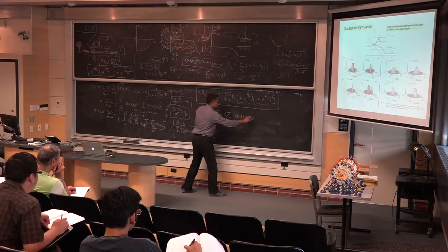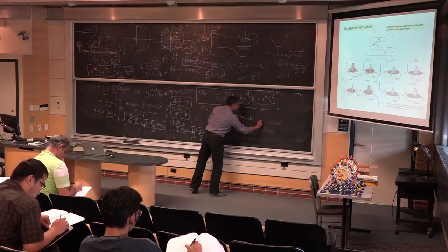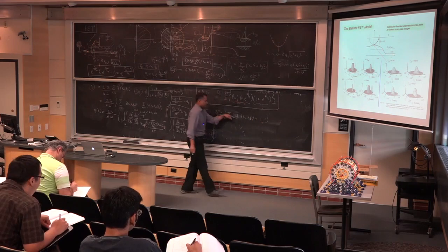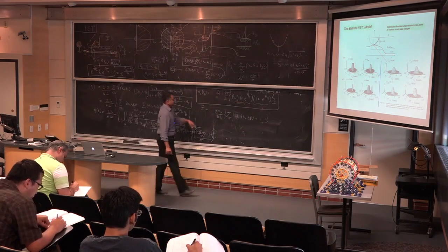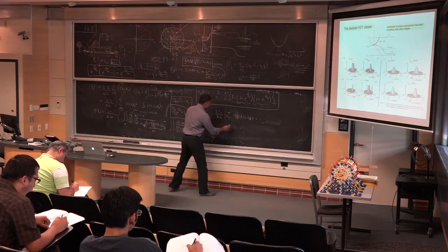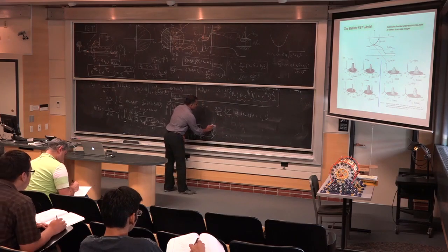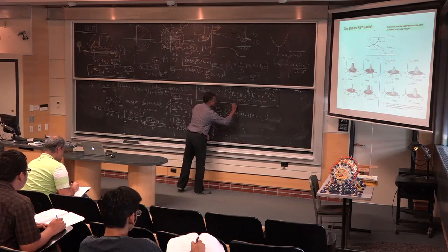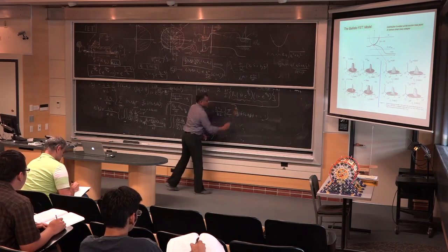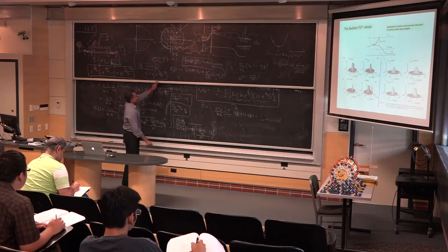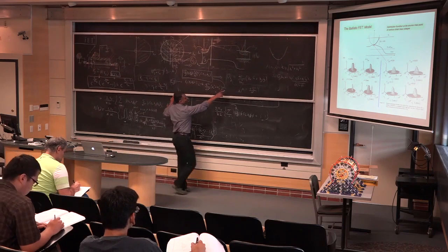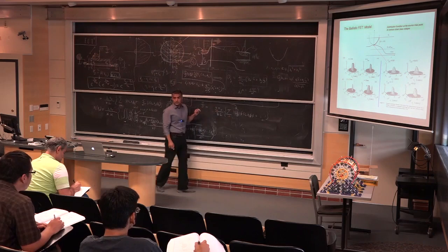Plus, again, there is something here which is going to the left, which I think you can write down. So there's the Fermi level of the drain and such things. But the more important point here is that you're taking the first moment of this now. There is a group velocity sitting in front. The group velocity we just wrote is actually a very simple relation. It's just that. That's the group velocity.